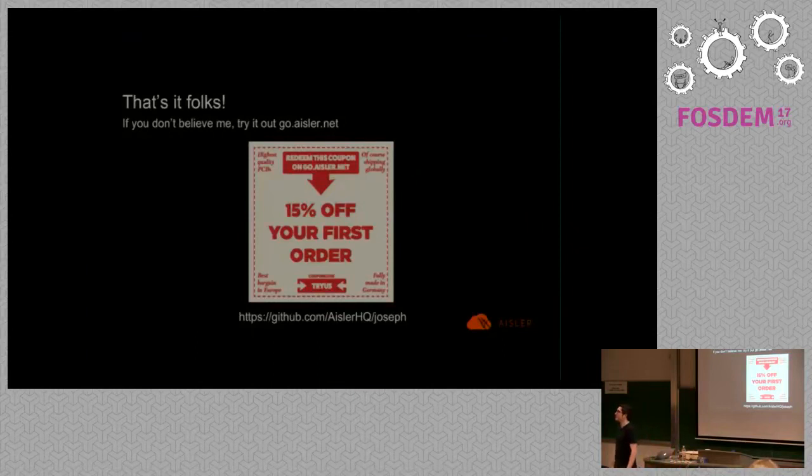Yeah, I think for some applications you have animation in your PCB tool. For example, if you do a panel of multiple boards, and for testing you want to test them all at once. So you want to have traces on the panel, so that you can just plug in your whole panel into a test rig, and all boards get tested at once, and then you can handle them afterwards. In that case, I think it's definitely required to do the penetration.